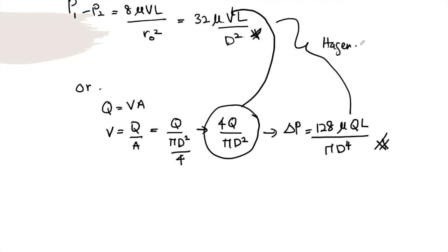You must remember that the Hagen-Poiseuille equation can only be applied to laminar flow and straight pipes, with no fittings. Okay, which means no fittings are allowable if you apply the Hagen-Poiseuille equation. So remember, laminar and straight pipes.